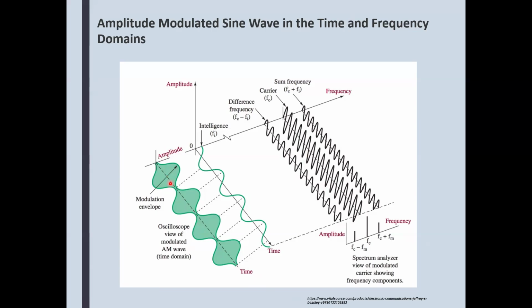We want to have some headroom, so if any kind of transient happens, we still have headroom and we don't overmodulate the signal, because that's bad for the equipment. But if we undermodulate, we are going to end up with a weak intelligence signal. It's going to sound quieter, and it's just annoying.